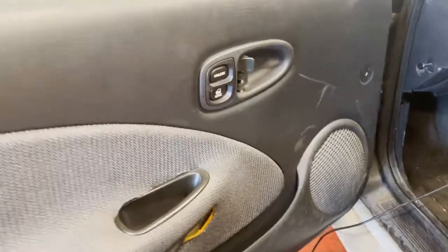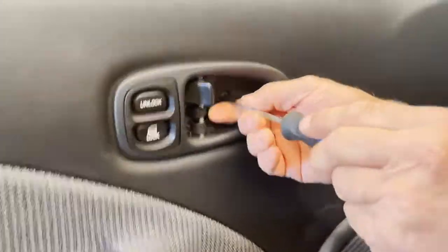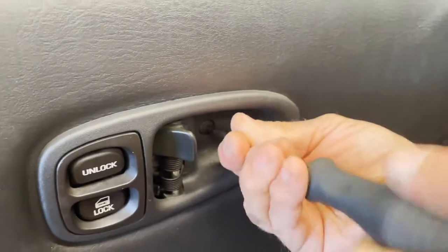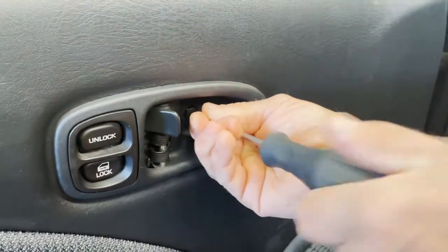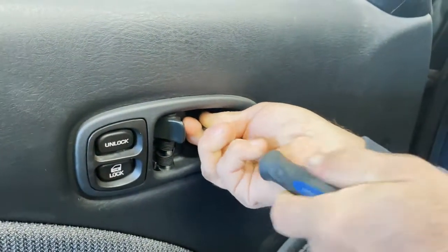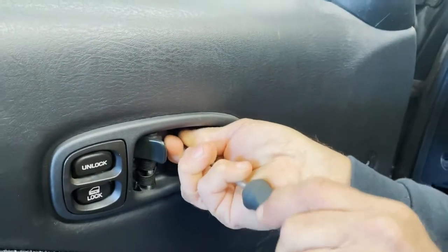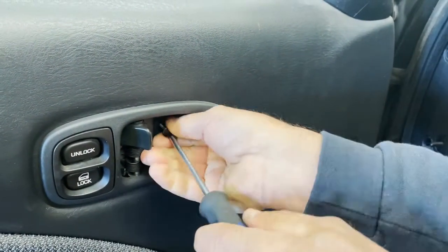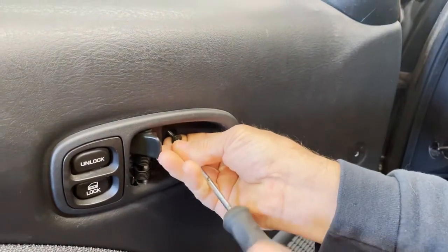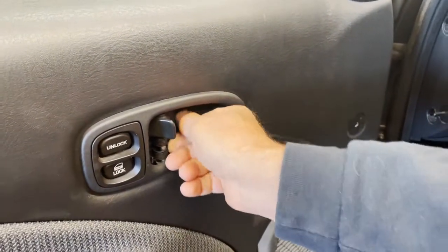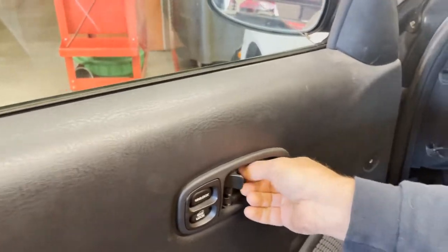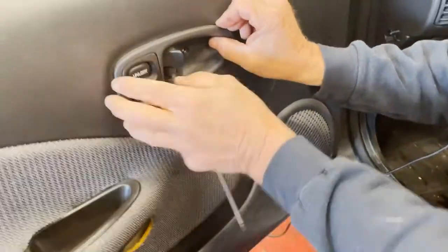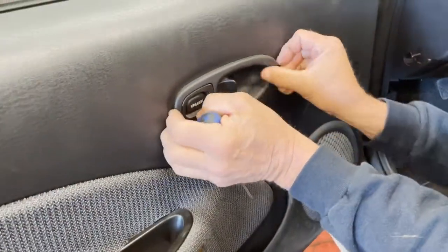Okay, the next few fasteners, I think they're just Phillips head. We're going to take one off here on this little cover for the door handle. Again, you want to be really conscientious about trying not to scratch anything or damage anything. People get really annoyed, and all these parts are very expensive. And I really need a little bit larger screwdriver, I think, but I got it. And when I take these parts off, I lay them somewhere where I'm not going to lose them, usually on the driver's floor.